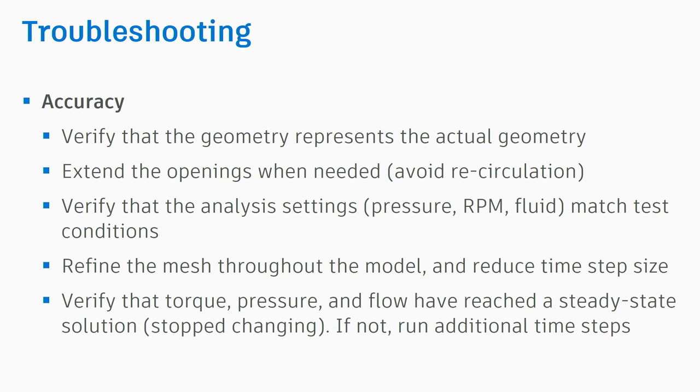As I said, you need to run through these options. Either extract the hydraulic torque values, or use monitor points, or track pressure. If you didn't catch that these variables did reach a steady state, run further time steps.